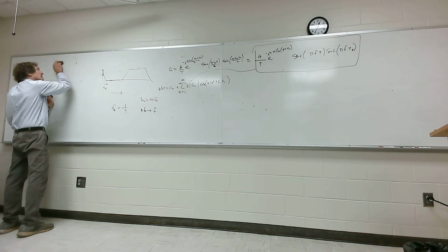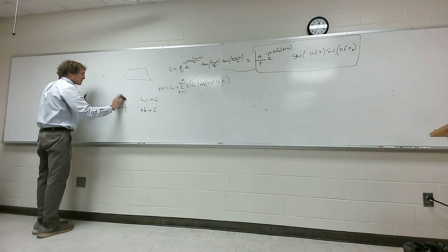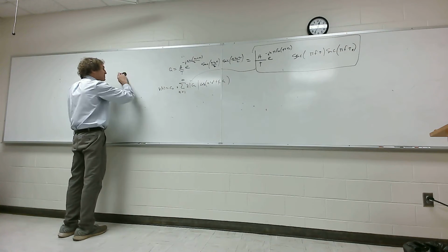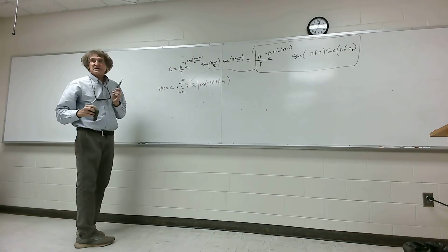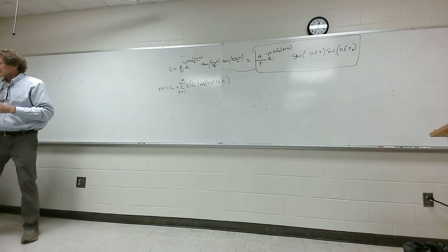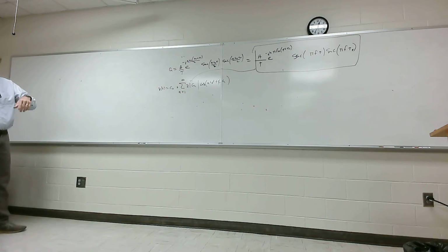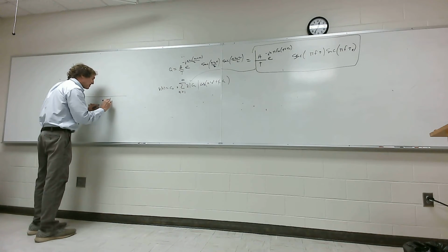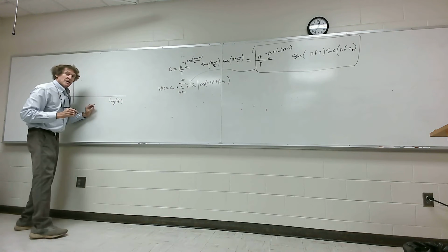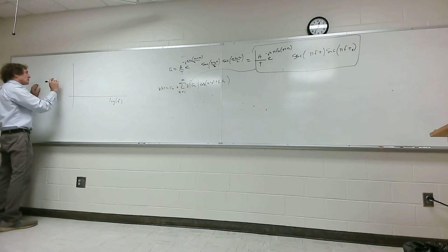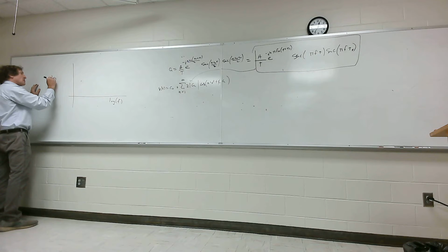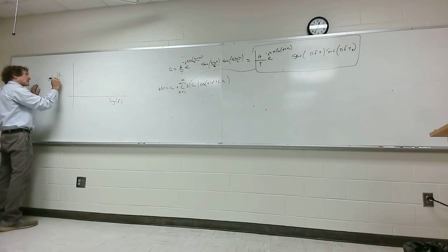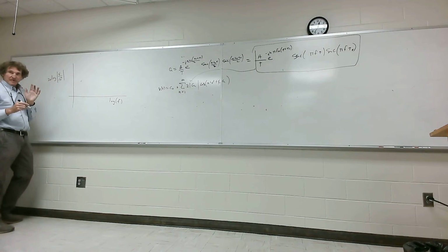When I come over here and do this, this is an approximate estimate. It's not exact, but it gives a worst case, and that's really what I was looking for. Normally when we talk about EMC in the real world, we look at the log of the frequency, and over here we plot 20 times the log of the actual voltage waveform over 10 to the minus 6.